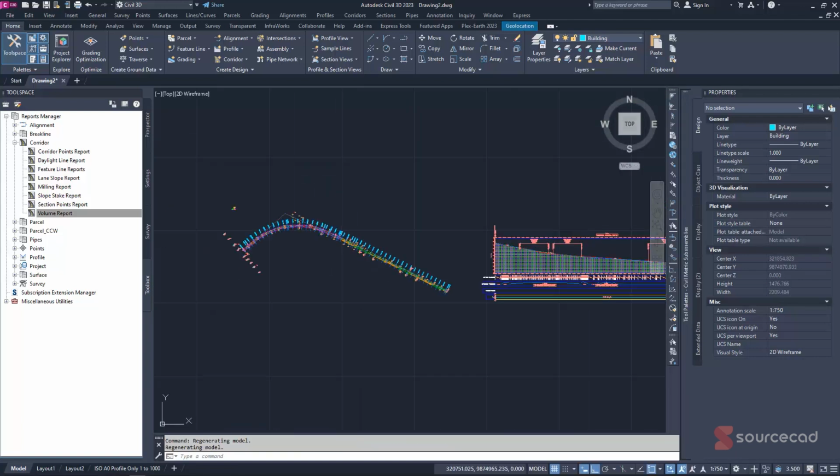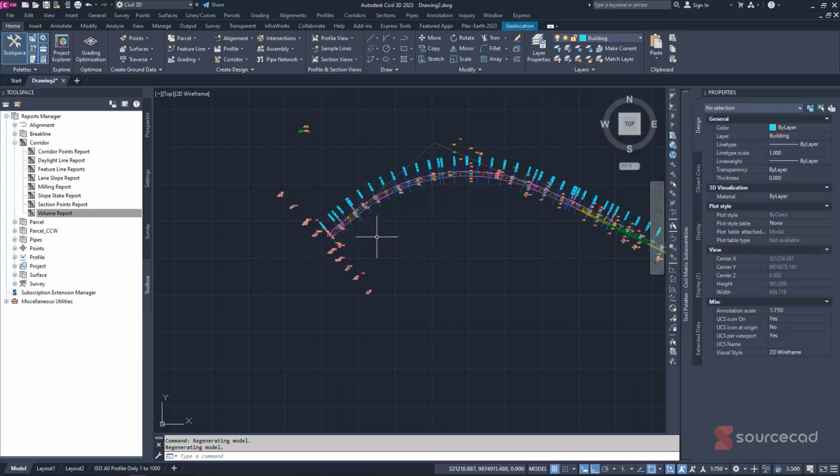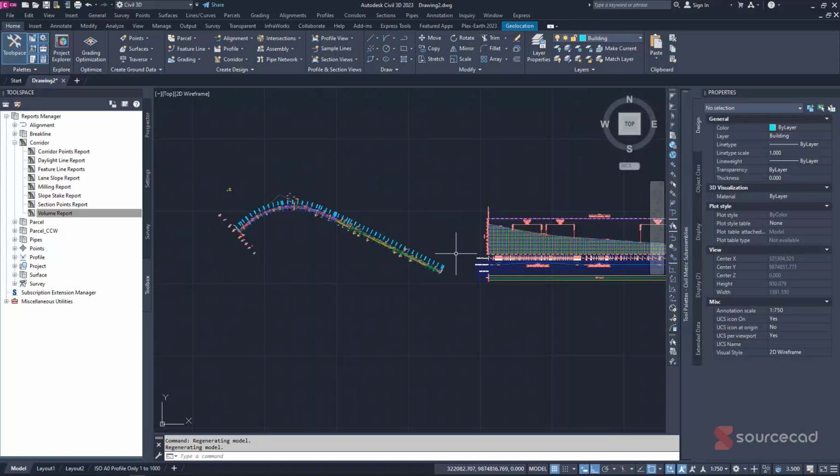quantity takeoff. Congratulations. So I believe now you understand and you appreciate how we generate our quantities in Civil 3D. So I have taken you through a step-by-step guide on how you first start your design in Civil 3D, where you import your points from Excel worksheets into your Civil 3D software. You create your surfaces, then you create your horizontal alignments.